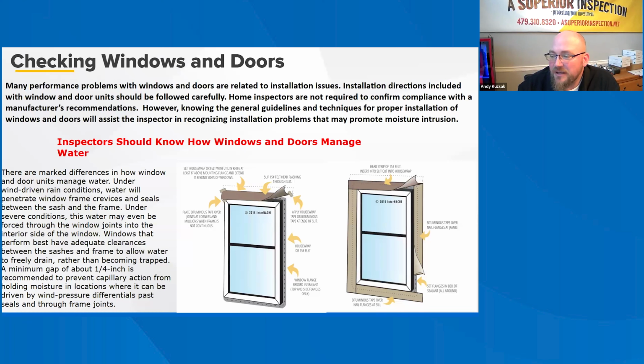The recommendations above detailing window and door frames can generally be checked by inspecting the manufacturer's technical specifications showing a cross-section of the unit, including dimensions, seals, thermal breaks, if included, and other factors that may create leakage paths, such as corner frame joints and mull joints in multiple window assemblies.